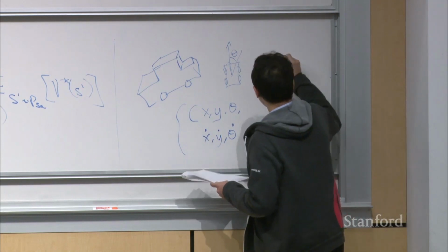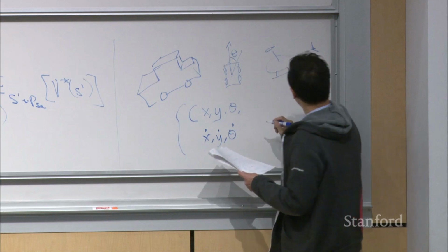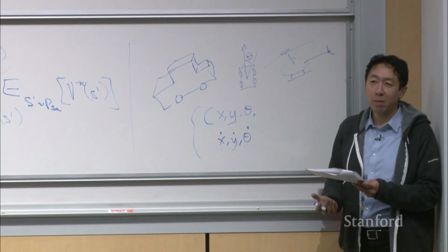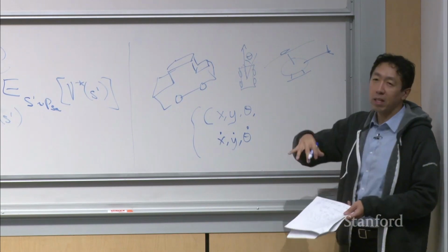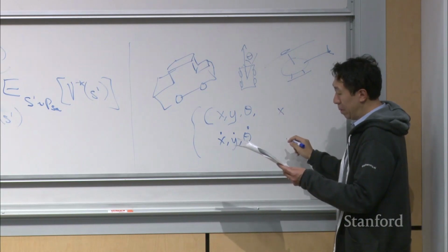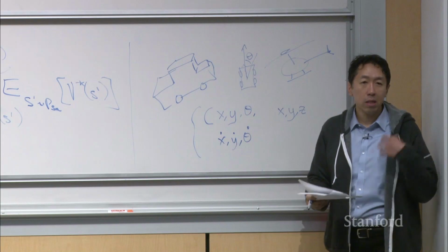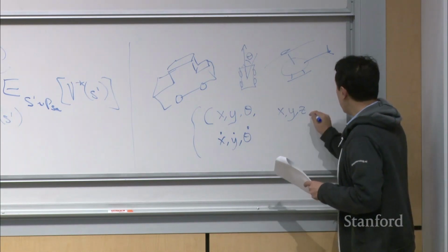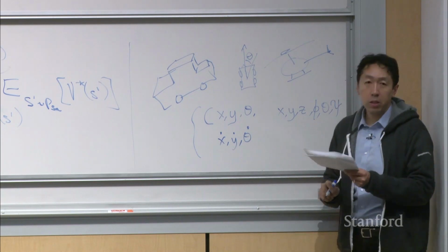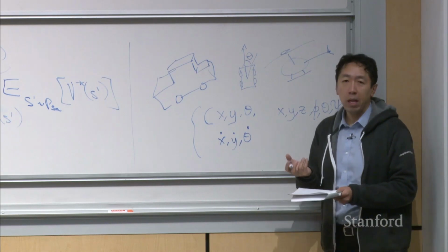Actually, all right. How about a helicopter? How do you model the state space of a helicopter? A helicopter flies around in 3D rather than driving around in 2D. And so a common way to model the state space of a helicopter would be to model it as having a position x, y, z, and then also a 3D orientation, which is usually modeled with 3 numbers, which we sometimes call the roll, pitch, and yaw, right?